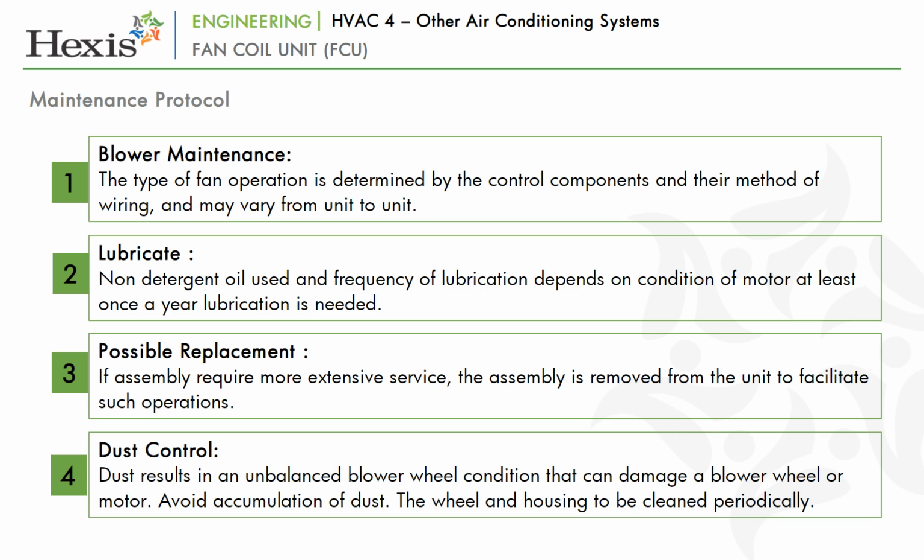Dust control. Don't allow dirt and dust to accumulate on the blower wheel or housing. This can result in an unbalanced blower wheel condition that can damage a blower wheel or motor. The wheel and housing may be cleaned periodically using a vacuum cleaner and brush, taking care not to dislodge the factory balancing weights on the blower wheel blades.